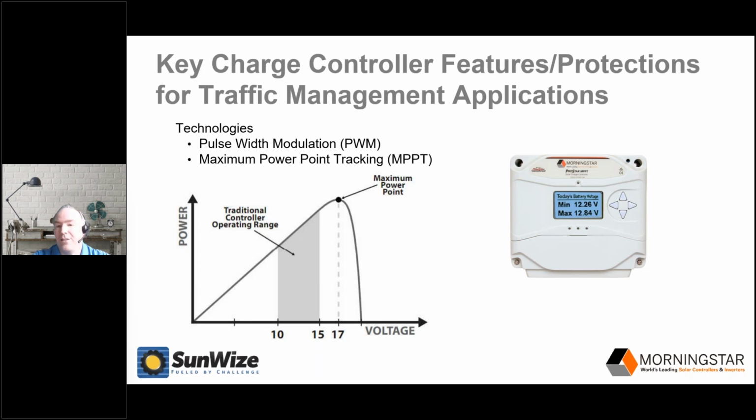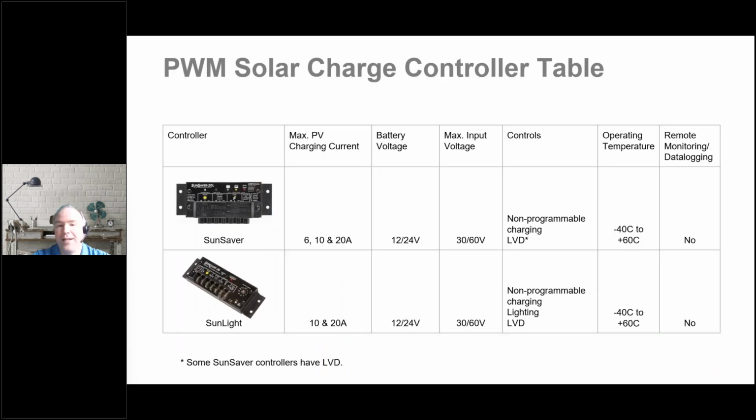They're more expensive than PWM controllers, but they provide more power to run loads and to charge batteries, especially in colder climates. They also support oversized PV arrays, and they can be used with 60-cell modules, which are often not suitable for PWM controllers. On the next several slides, we provided some charts that list the most popular controllers for traffic management applications and some of their most important specifications.